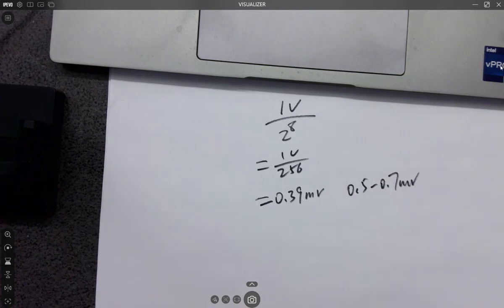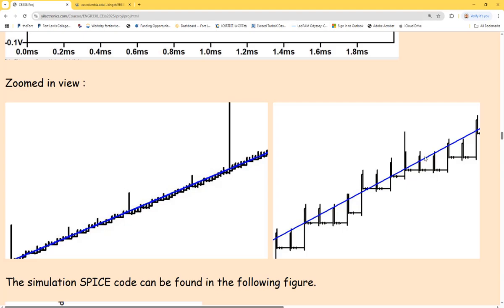Right? So that's something you want to look at, and also you plot this curve, and eventually you have to look at the points, find out, maybe plot the entire DNL and INL for each point and make an average. Or you can plot a diagram to have all the DNL and INLs being plotted, and eventually just display the entire result, instead of an average value. So eventually the DNL and INLs will be a range.